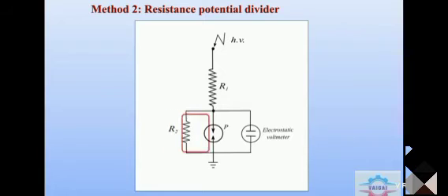To avoid these transient voltages, voltage controlling capacitors are connected across the elements. A corona-free termination is also necessary to avoid unnecessary discharge at high voltage ends. Therefore, a series resistor with a parallel capacitor is used for linearization of transient potential distribution.